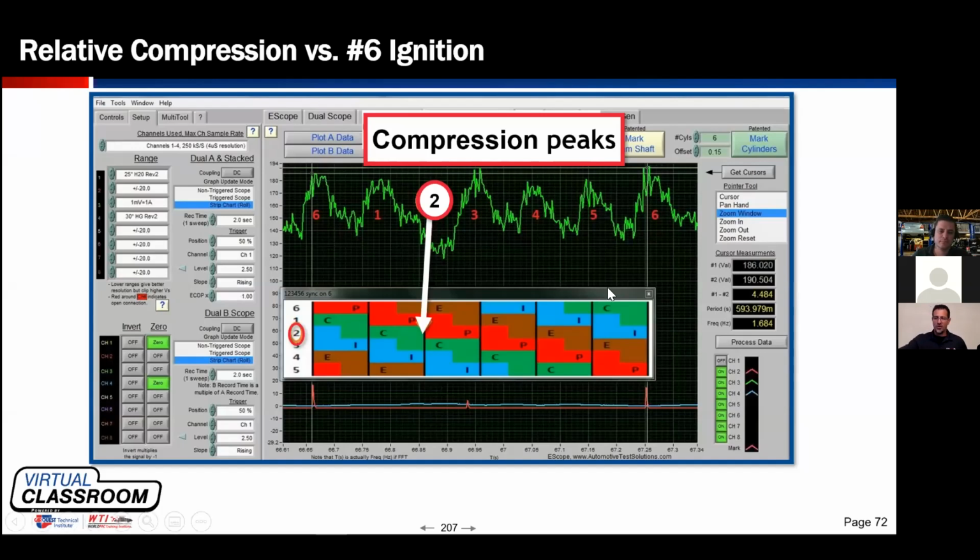So the ignition system is going to be loaded. We're going to have a higher kV demand when a cylinder is under compression than when it's on its exhaust or waste event. And that's exactly how compression sense ignition works on some of these systems. So we see a high firing kV and a low firing kV. We know the high firing kV to be that of our compression stroke, and when it repeats itself, that's 720 degrees later.